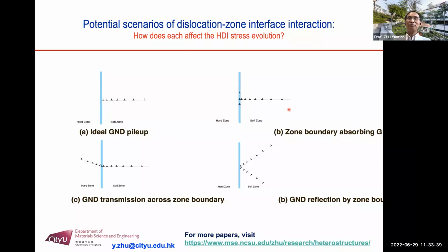Another scenario is all the dislocations got piled up. However, the dislocation at the front are pushed into the boundary. Then it got some clamp and stayed in the boundary. So you can put more into it. So this type has also been verified by in-situ TEM.